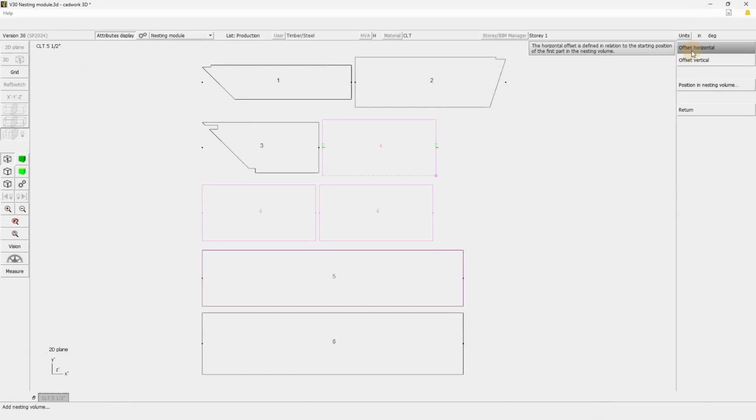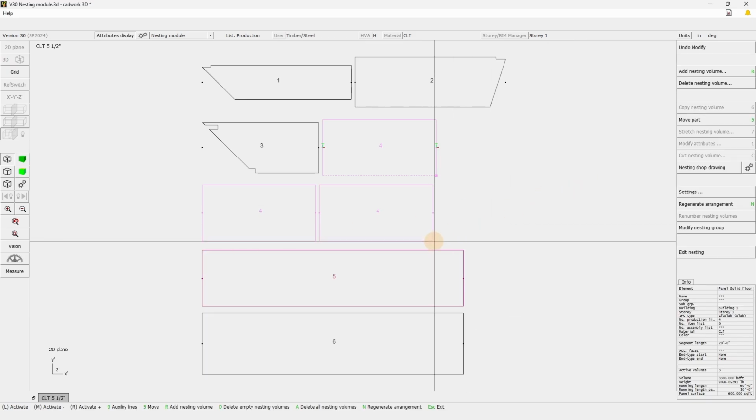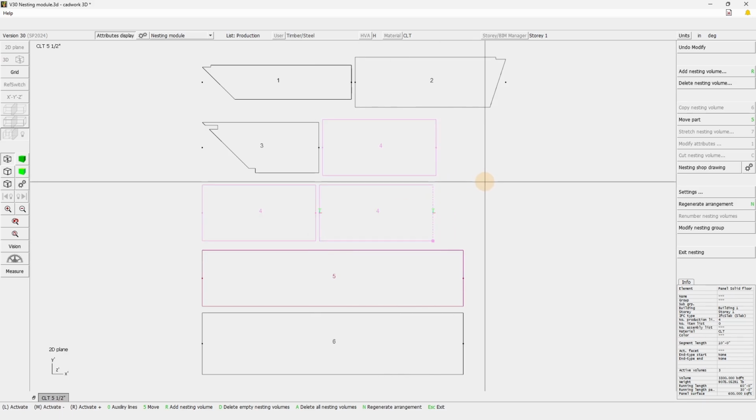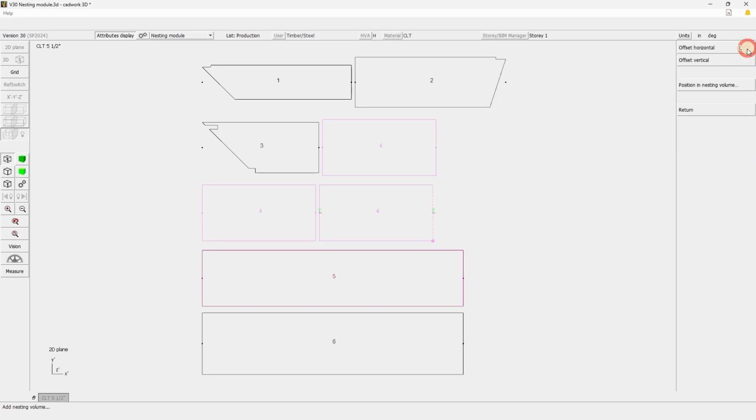So basically, if this element is at the bottom of the nesting volume, do you wish to add an inch or a quarter inch from that side? Knowing that our elements here are 10 feet and we've set that these volumes should be 11 feet wide, actually let's do this and add an inch in both directions. And here we will simply run that length optimization on these 3 active ones.